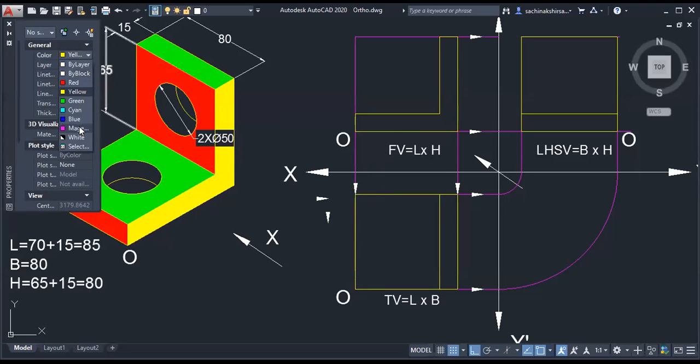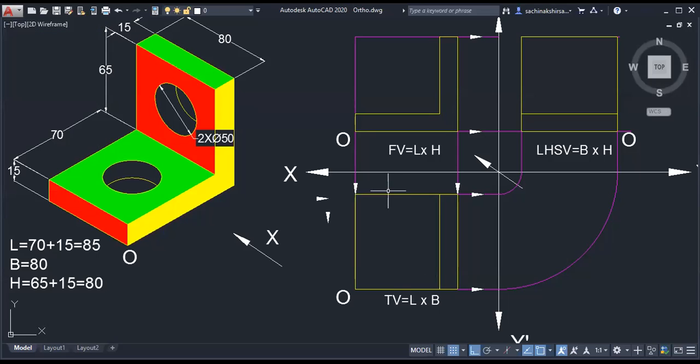So we will locate the center by a feint line. So what is this dimension? Let us look at 70. For both we have to draw the midpoint. From here you have to go 35, and whatever it is there, 80. Then similarly this to this. For this surface you have to locate the center by a feint line. Yellow colored lines are dark lines and the pink colored lines are feint lines.